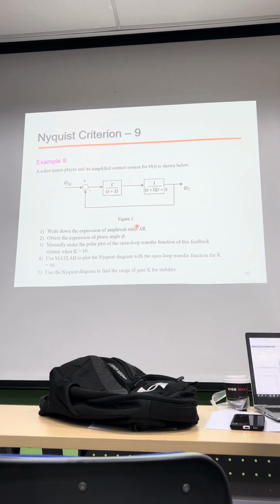So we have to get the transfer function and come back to this. The last one will come over. If this is the phase angle, another 4 marks, just writing the formula, substituting and everything. Then make the manual polar plot. You can use Excel to draw it because you have the amplitude ratio formula and phase angle formula. Put in the omega value, then just drag it, so you will get all the values. Then you can make a plot on it using Excel.